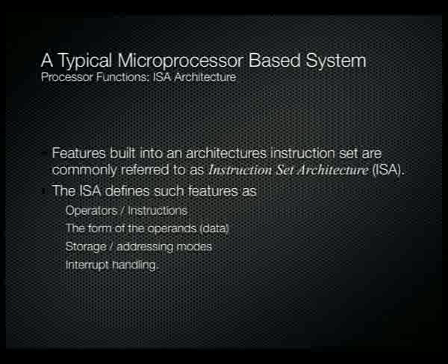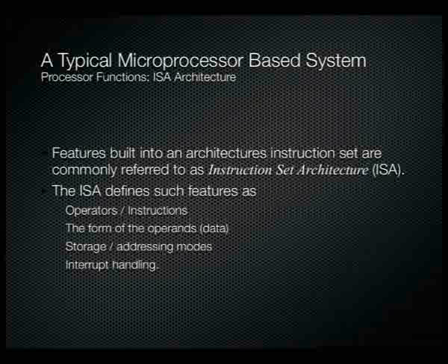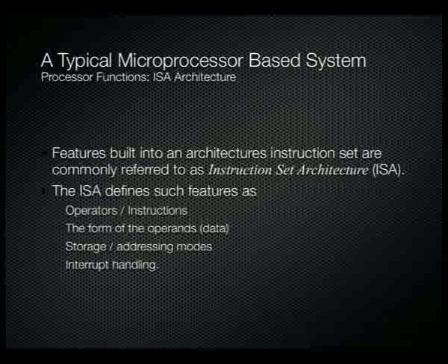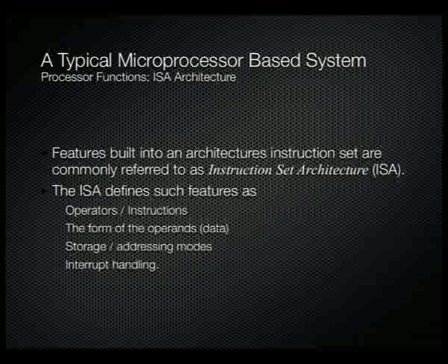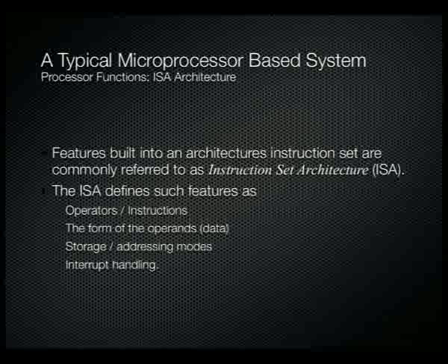There is absolutely no point in having functional units inside a microprocessor if there isn't an instruction to enable those functional units. So the architecture of our microprocessor is heavily defined by the instruction set that we have for that microprocessor. The instruction set architecture is effectively the instruction set which defines the architecture of the microprocessor. And of course, depending on how quickly you want those instructions to operate, the architecture of the processor is defined in such a way to ensure that the timing is met for those instructions.